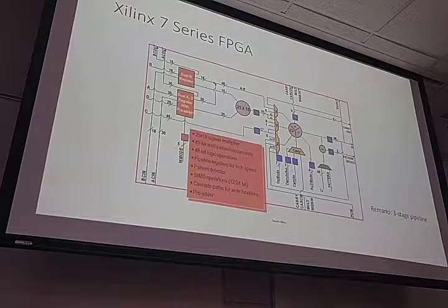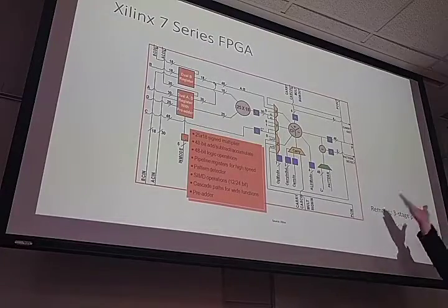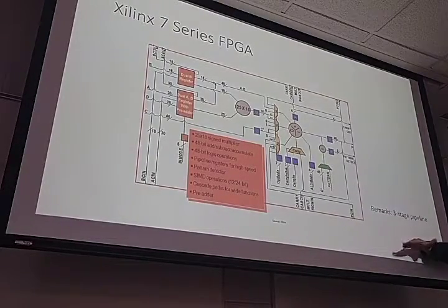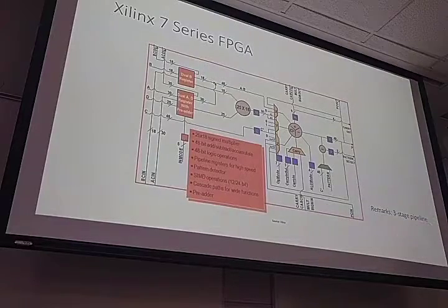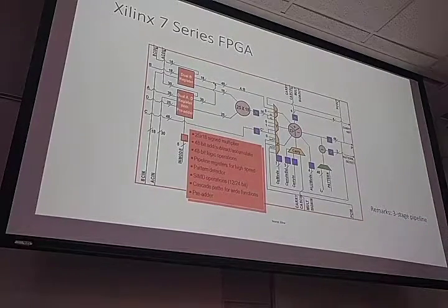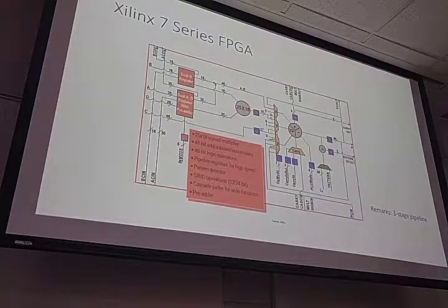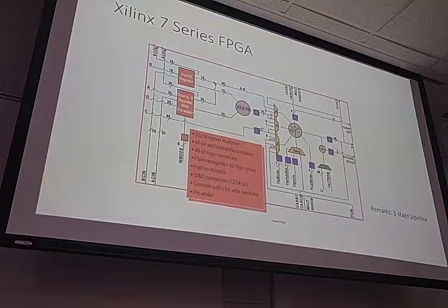We're going to multiply 2 numbers, which, if we were using a latency-prone RTL design, for that initial table that we've shown, would take 5 clocks. If you are multiplying two 16-bit numbers, it would take 16 clock cycles. So it's a great advantage, and they also use less power. So you can go ahead.